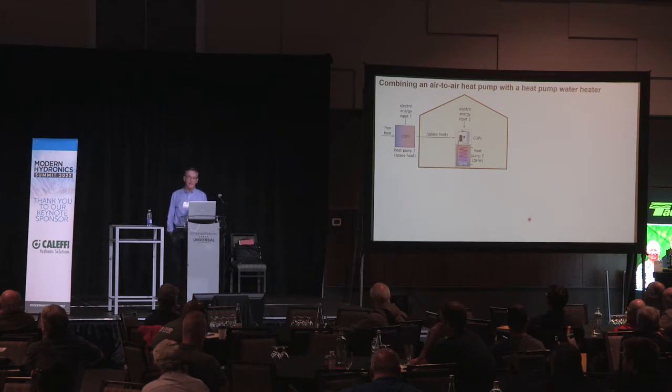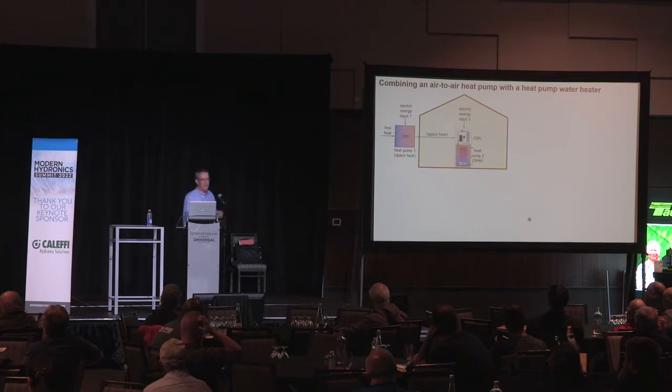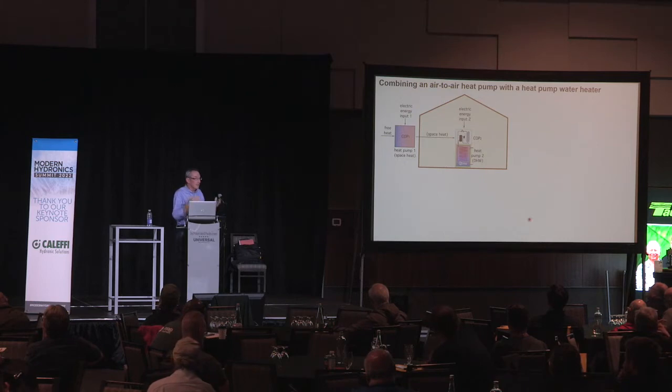Now, within the thermal envelope, we have the heat pump water heater. And I'm going to tell you the assumption that I put in here, which is partially valid and partially invalid. The assumption is all the energy that that heat pump water heater gathers was put into the thermal envelope by heat pump number one there, okay? So we're taking away things like internal gain, okay? We're separating this from the standpoint where maybe in some type of a commercial environment, you might have surplus heat in a certain area that you're trying to get rid of anyway. That's a great solution to put a heat pump water heater in if you have a domestic water load.